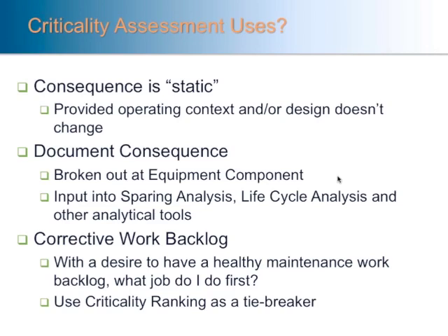What sort of critical spares do I need to hold on hand? What am I looking at from a life cycle perspective? And other analytical tools to explore reliability further. And one of its most powerful uses is in the form of prioritizing corrective work backlog. It's very good to have a healthy backlog, but where you run into situations of not enough resources to perform a particular job, criticality ranking can be used as a tiebreaker.